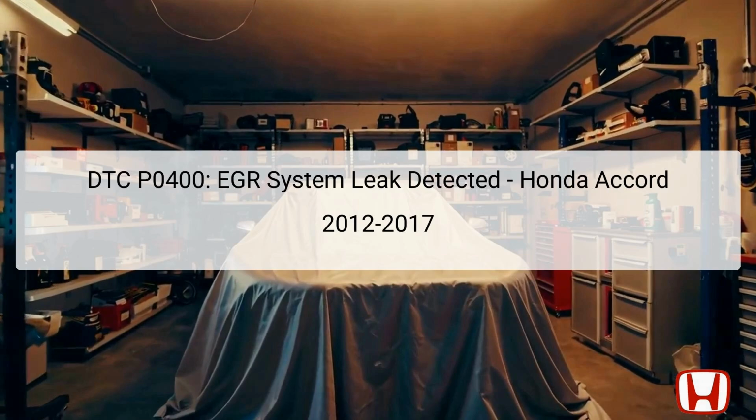The Diagnostic Trouble Code, DTC P0400, refers to an issue with the exhaust gas recirculation, EGR, system, specifically indicating a leak. The EGR system plays a crucial role in controlling nitrogen oxide emissions by recirculating a portion of the exhaust back into the engine's intake manifold.